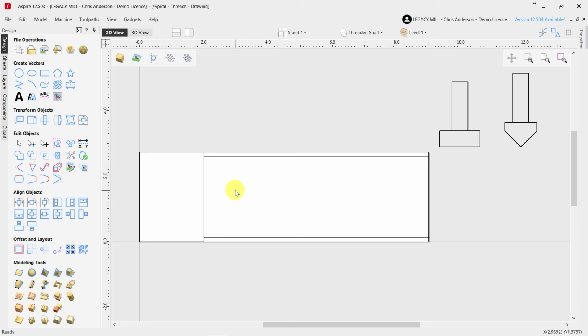And we're going to have a blank here that, in this case, we don't need a super long threading sample like we've done in the other videos. So this one is a 9-inch diameter blank. And I have a square section here at the beginning. And then we have a turned round section here for the rest of this process. Now the turning round process has already been done. So that takes the surfacing cutter and it starts at this position and it travels down that material until it gets to the end and then lifts out. And I've already done that on the machine.